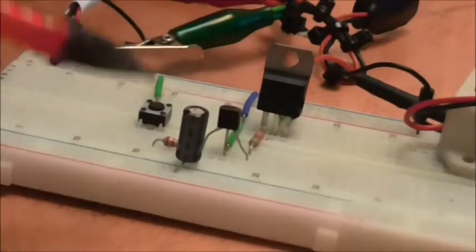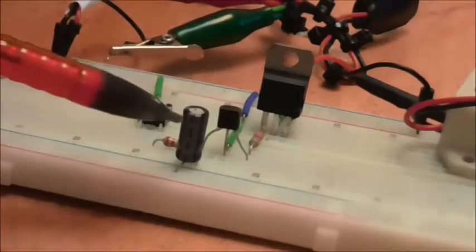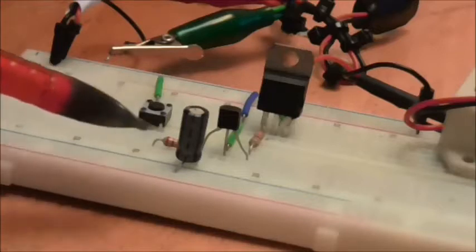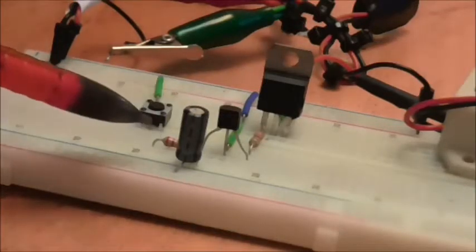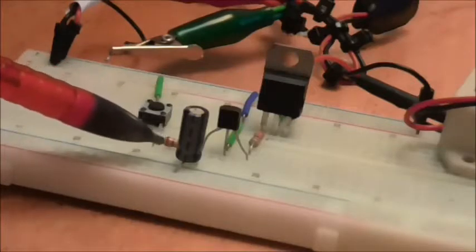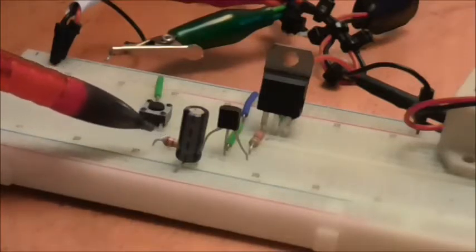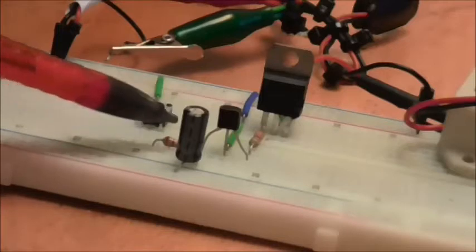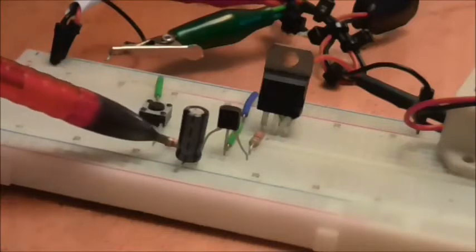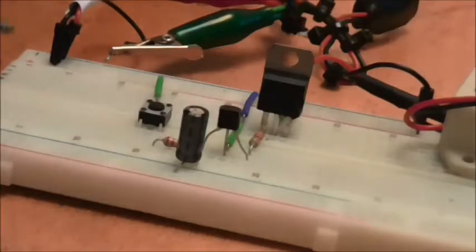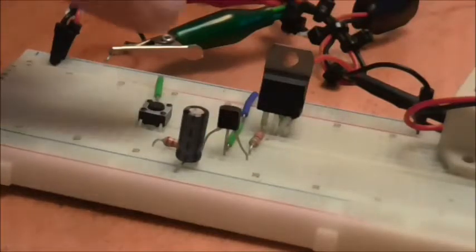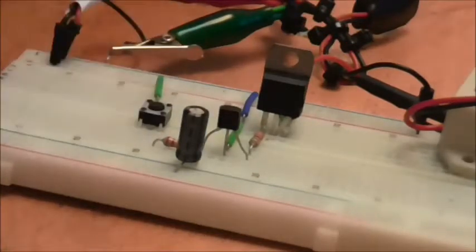and we can see a capacitor, and that capacitor is supposed to be there to shunt away AC transients. And as I was building this circuit it occurred to me that it may well be in the wrong place, because what it could do there is it could charge, and it would be charging very slowly through this resistor, and it could rob current from the buzzer here. Well, I'm going to press the button and we'll see what happens.